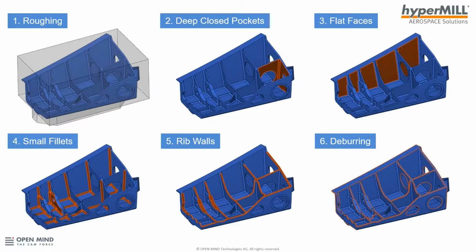The fourth topic is the fillet radius. As I said earlier, because of weight issues, these radiuses are getting ever smaller, so it is always a challenge how to machine those. Of course, you can get longer and longer tools, but then the diameter is quite small. So this is really a challenge to machine in an efficient way. People often end up scanning this with a ball mill type tool to get the job done. But we're going to take a look at how we can do these things.